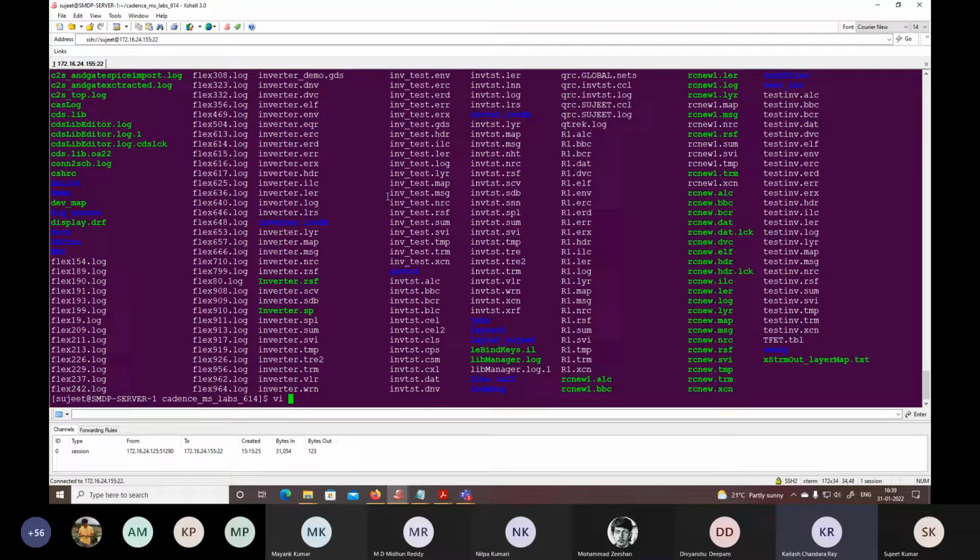Go to the layout window and import this one. You have to again open the layout window. It will not open like this, right? No, sir. It is only the geometrical data. We cannot open it as a layout. You can open it when you go to the layout window, the way you did the export. So we have to provide the layer map file for this. Have you given a layer map file? This is the generic. Just try to open it. Okay, sir.